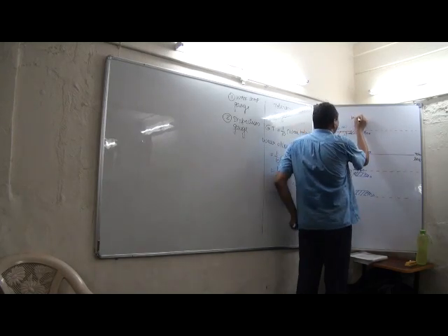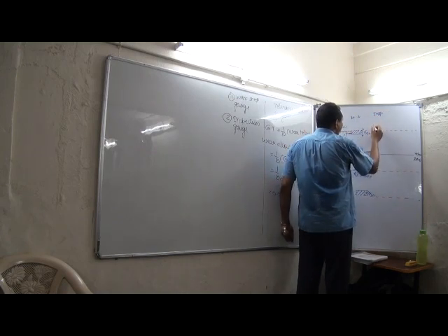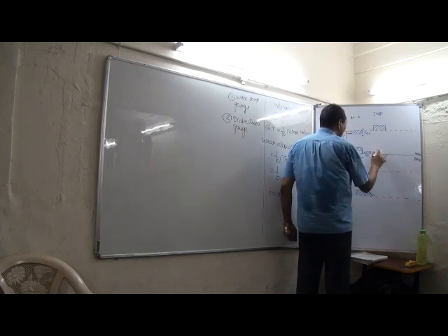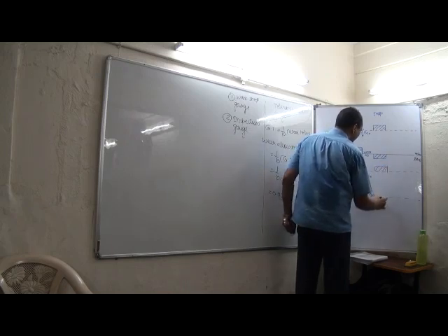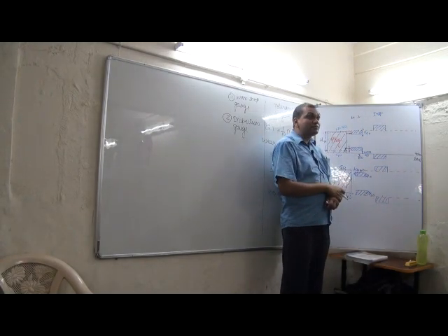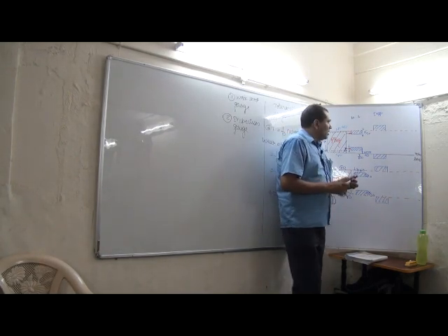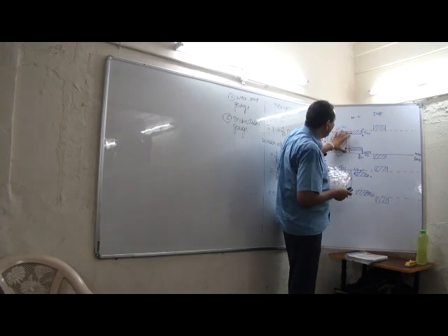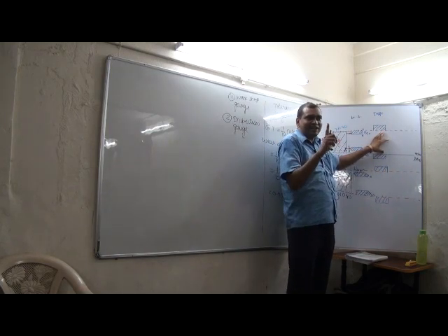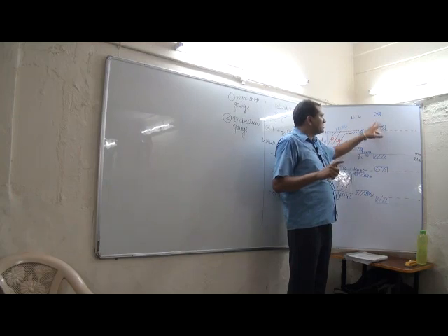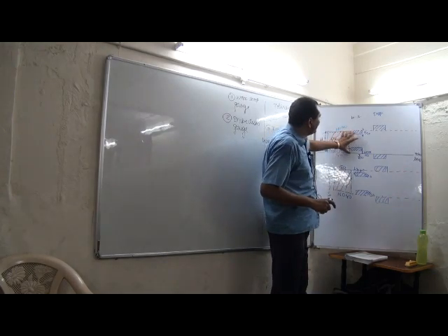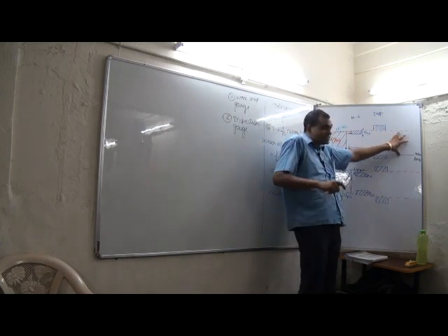So this is the workshop, and if you see inspection, the tolerances will be away from the work tolerance. Like this. This is go, this is no-go. Tolerance will be away from the work tolerance. So we can see here, whatever holes are coming in this range are accepted. Everything is accepted, so we are not rejecting any good part. That is the tolerance on the go gauge, tolerance on the no-go gauge. So whatever holes are coming in this range, that is within the tolerances, will be accepted by the gauging system.